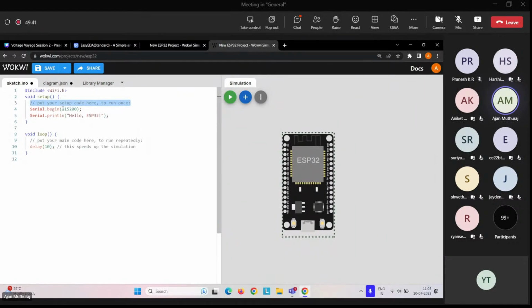It is a large baud rate, but it is not that important right now. Normally in Arduino IDE, you need to change this baud rate at two places, while writing the program as well as while seeing the serial monitor. But in simulation software, there is no such problem, so you need not worry about it.